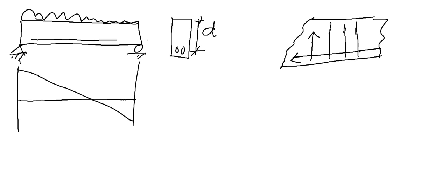Now, what is shear failure? Shear failure is typically at d distance from the support, and it is a diagonal type failure. Diagonal failure, angle is 45 degrees. Now, every time it will not be 45 degrees, but based on experience we found that shear failure is typically diagonal at 45 degrees, and it occurs at d distance from the support.